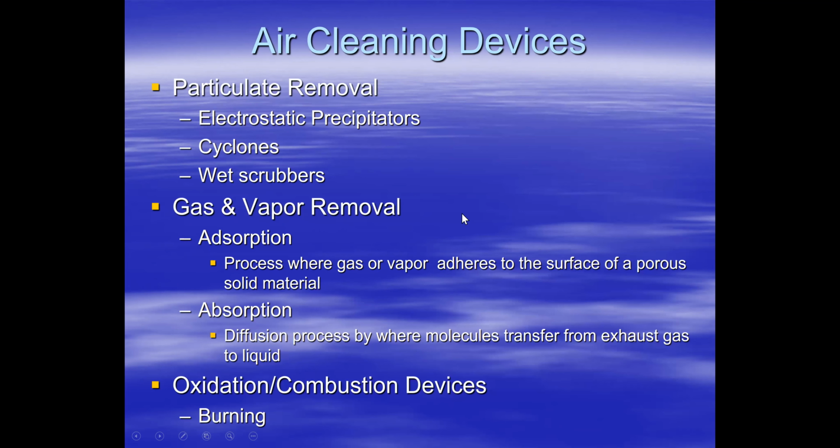For air cleaning, we've got particulate and gases and vapors. Typical particulate removal includes filtration, which for some reason I left off, and electrostatic precipitators that use charge. Cyclones work in the same manner as the respirable cyclone that we used in the lab. Air comes in with a spin. You've probably seen those on top of industrial facilities; they look like round boxes with a tapered bottom. Basically, they use impaction. The particles have the velocity of the air, can't make the turn, impact, fall, and get collected.